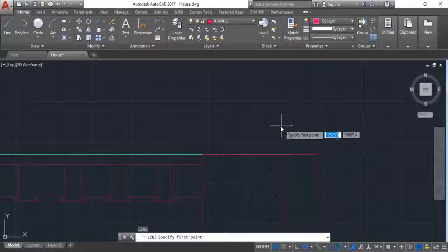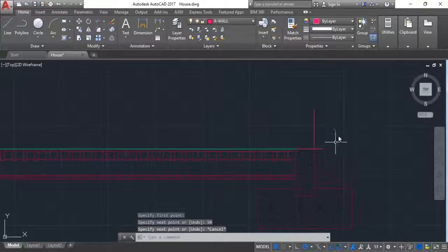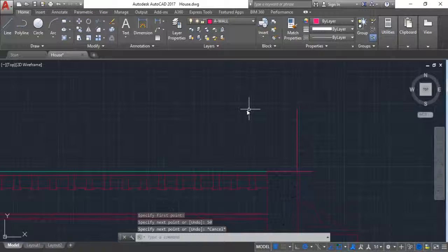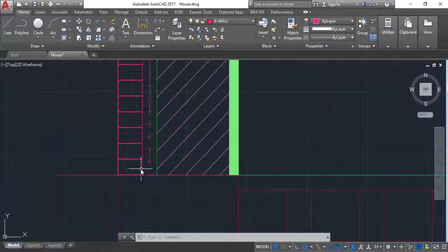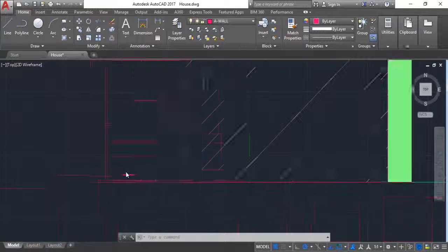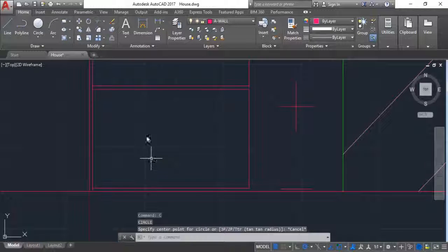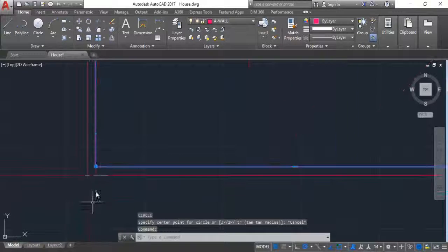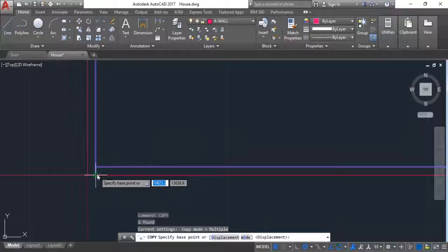So let me close this line, and our height is going to be 50 centimeters, and then we're going to put the windows over there. But first of all, let's make that 50 centimeters of our section with all the necessary elements. Copy and paste everything that we have on this wall to our new wall that we're going to make.